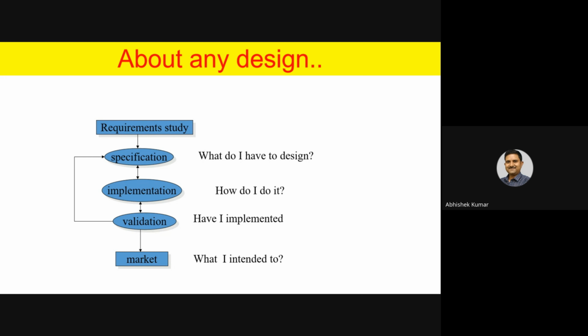Specs are like, in our IC, how many inputs, how many outputs, what should be the range of power consumption, what should be the range of area, some mm square or micro mm square. Similarly, what is the delay, how much delay is expected. Now, if they're working on RF work like microwave or antenna, what are their specific limitations like SNR, decibel gain, noise margins? So we have to think about all types of electronic spec.